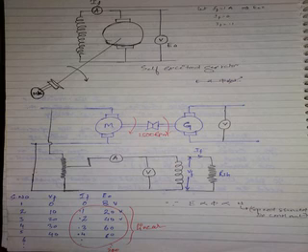So you will get point P somewhere here in this region. So this is the maximum voltage the machine can build up. Now imagine the field resistance is increased beyond RC. The field resistance is increased above RC value. How will the line come?